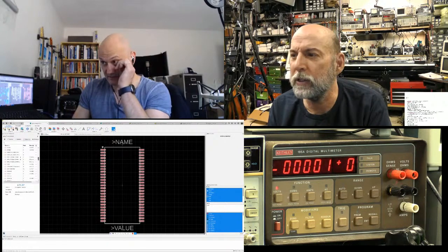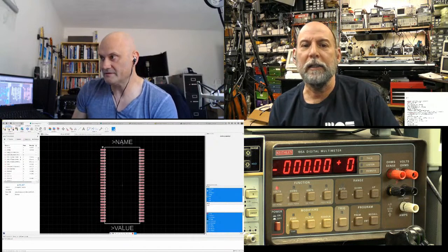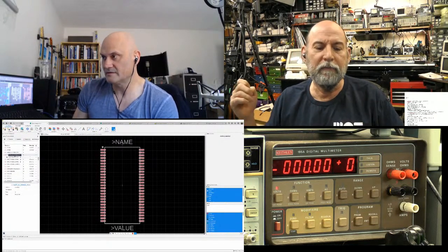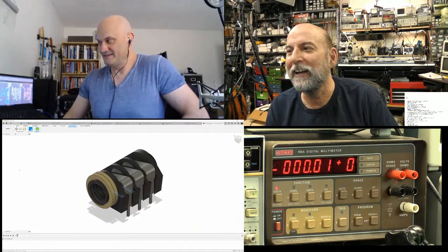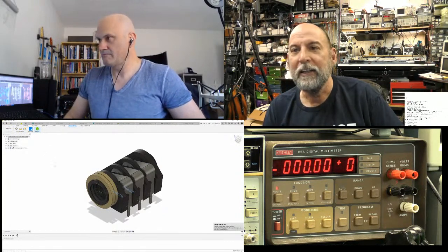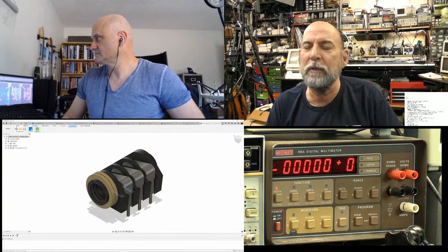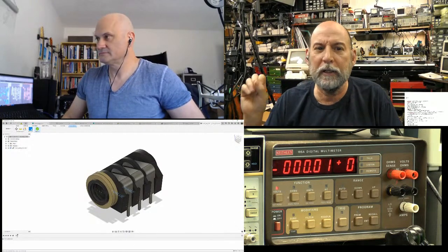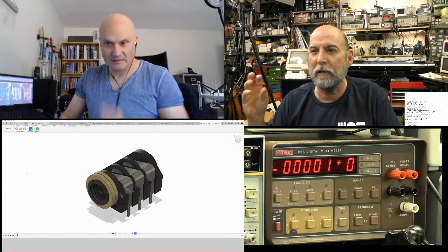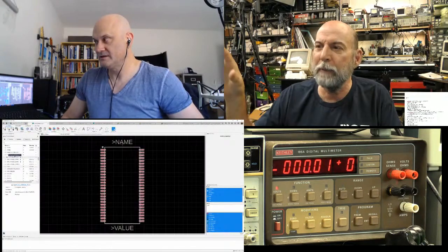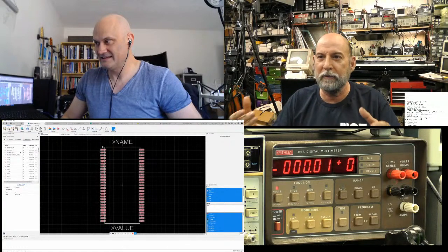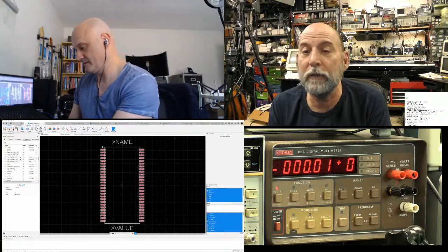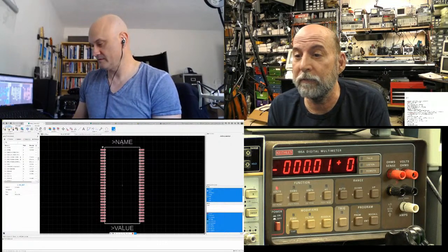Yeah. I had posted a link to Alan Wolke's video where he had a little XY generator for a scope that did the Tektronix logo. I loved that, and it did the wizard icon. Yeah, yeah. And what I was thinking while you were talking is you could do that inside an FPGA, and it looked to me like the code broke it into quadrants so it could deal with it 8 bits at a time instead of trying to do 16-bit addition. It looked like it said pick a quadrant, do 8-bit math while you're inside the quadrant. But if you were to do that inside an FPGA, you have both the memory and the ability to add 16-bit numbers together or whatever, 24-bit numbers, counters and whatnot to make your vector draw.